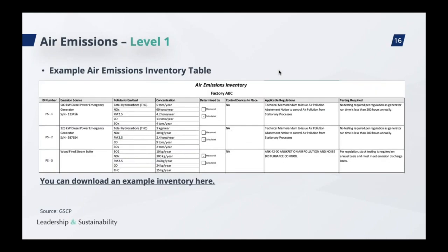The following elements are suggested to be included in the inventory: the pollutants known or likely to be present, quantity of each pollutant emitted, emissions points, any control devices, frequency of monitoring, compliance with legal regulations.